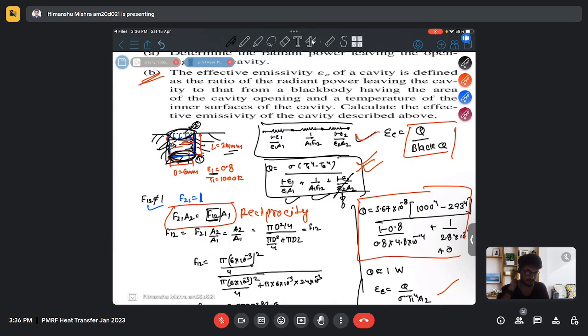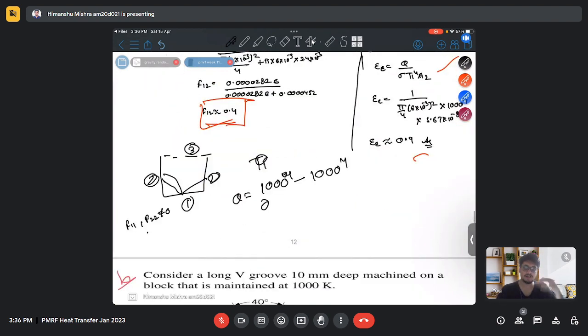It will have extra resistance due to surface 3 and the space between 3 and 2, and 3 and 1. So the resistance becomes much more complicated, and there will be multiple ways of heat transfer. From 1 to 2 it will be 0, and there will be only heat transfer from 1 to 3, and you need to accommodate the suitable resistance between 1 and 3 itself.